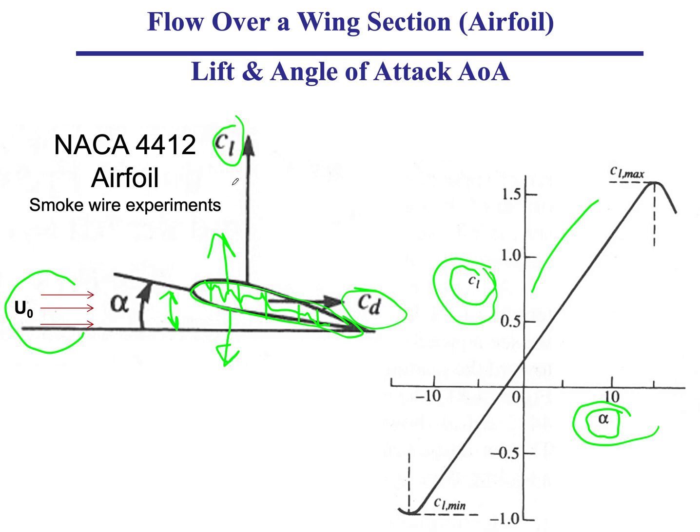And even though the lift force in the small case, the 1 centimeter case, could be 1 Newton, in the case that is 1 meter or 5 meters, the lift force, instead of being 1 Newton, could be 100 kilonewtons or so, depending on the problem parameters. But still, as long as I have the same section, I'd expect to get the same dimensionless lift force with the angle of attack. So it's a very powerful tool, using dimensionless numbers to describe experimental data.